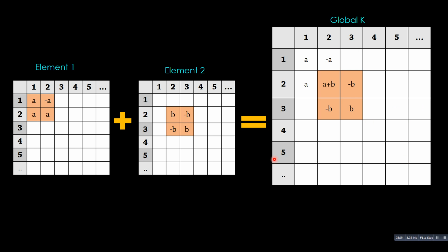The next thing would be to apply boundary conditions, partition the matrix, and finally solve the system of equations. Partitioning is simply discarding those rows and columns corresponding to the degrees of freedom that are fixed or specified. We'll take a simple case here where the specified degree of freedom is 0, that is, the degree of freedom is fixed.